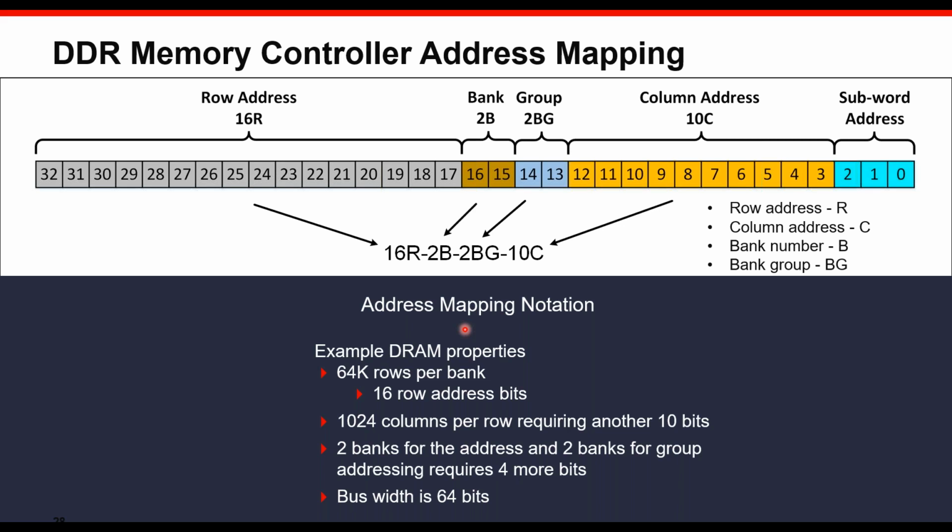Now, we talked about the DDR memory controller. There are a lot of different DDR4s or LPDDR4s that this can connect up to. Make sure you understand which one you're actually connecting to. The definitions are always typically in the name. You're looking at the row address bits, the column address bits, the bank groups, and any other information that you can fit in the last few bits that are available.